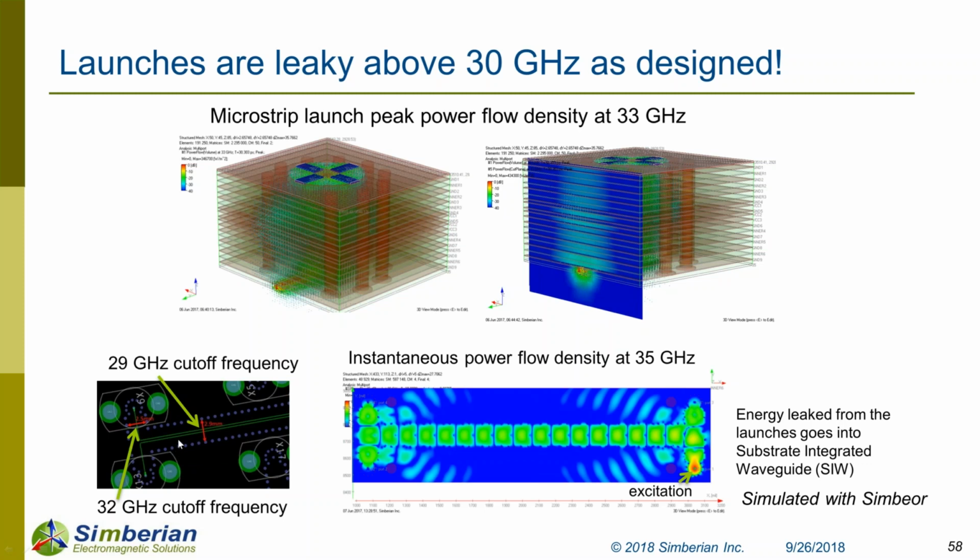Sometimes I get questions: on those boards all the layers are ground and stitched together, and that's not realistic. In reality, you have ground, signal, power, signal, ground, or something like this. And I usually answer, just forget about it. If you want predictability and you want your interconnects to work as expected, just use ground, signal, ground, and stitching at this location, and moreover stitch it along the transmission line. That ensures it, and you saw how important it is, even for PAM4 56 gigabit per second.